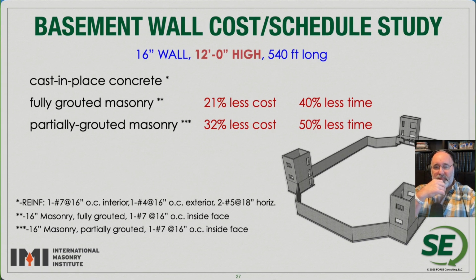Really, when we get into basement walls, maybe we ran into the design being at 16 inches on center. At 16 inches on center, we're basically at half the grout, but we still have a lot of grout in a basement wall. So even though we're saving quite a bit on grout, it's not going to be quite the overall savings that we saw for just the stem wall.